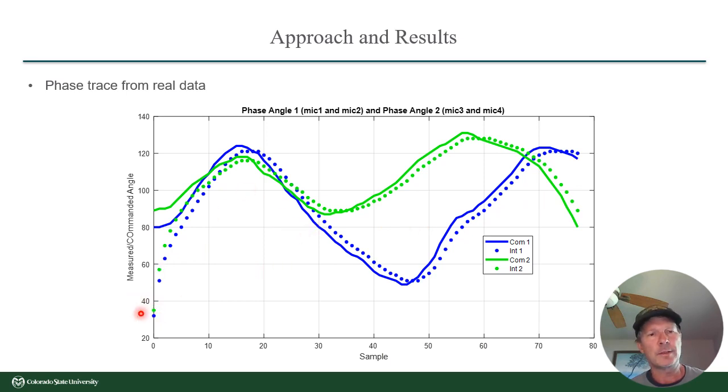And you can see the dotted lines here are the integrator that I mentioned above that I implemented. So you can see the integrator starts out not caught up to the signal, but it does catch up to the signal. And you can see too that it's got a little phase delay between the commanded and the integrated position, but that is so small it just doesn't matter for our purposes here. So the integrated value is the value that we sent out to the servo motors.